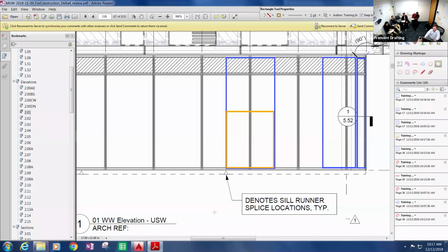It's because the head anchor is taking this wind load, because the wind load is applied to the face of the wall, right? So as we go to figure out what the anchor is here, it's half of the height. So anchor to anchor, half of it. So tributary area really only is calculated to verify the anchors of that mullion.